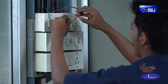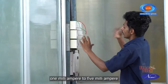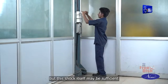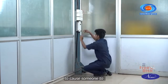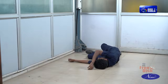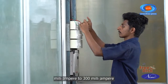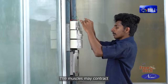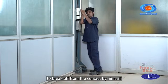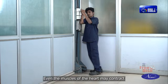The effect of electric shock at very low current levels of 1 milliampere to 5 milliampere may only be an unpleasant tingling sensation. But this shock itself may be sufficient to cause someone to lose his balance and fall, resulting in casualty. At higher current levels of 10 milliampere to 300 milliampere, the muscles may contract and the person will be unable to break off from the contact by himself. He may lose consciousness. Even the muscles of the heart may contract.